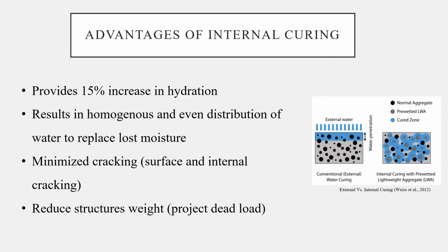First, let me briefly introduce the meaning of internal curing. As we all know, concrete after pouring needs to be cured in order to minimize the water loss due to evaporation, and that's a requirement to avoid excessive shrinkage, cracking at early age, and loss of compressive strength.